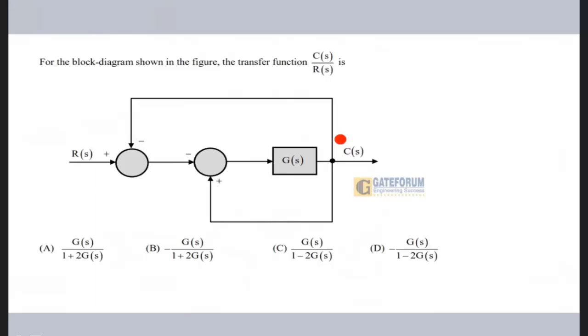So see, whatever complex block diagram they have given, you can always simplify by taking variables. Here I am just concerned about the output and input, and I can consider any variable here, x, y. So you can do it by any method. There are several methods. You can also go by Mason's formula, signal flow graph and all.